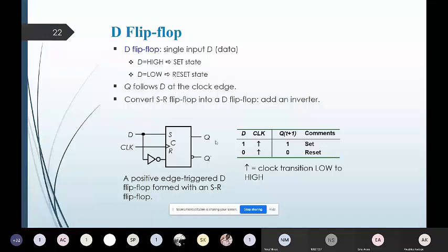And that's why in the truth table, now you can observe for the positive edge triggered D flip-flop itself, because I have shown here the clocks which are with the upgoing arrows, and D will be either having the input value as 1 or 0. So if D is 1 with positive clock edge, then the next state will be definitely with one value, which is said to be the set state for the D flip-flop.